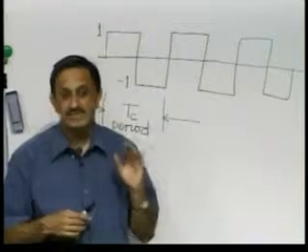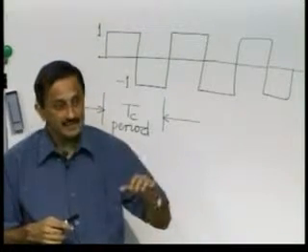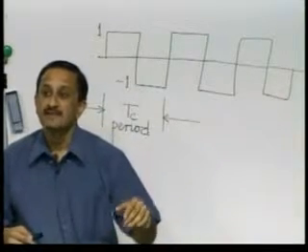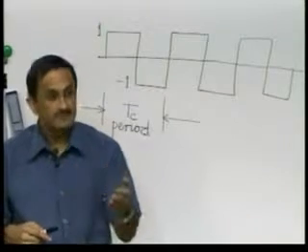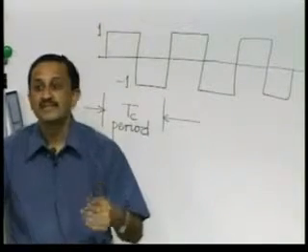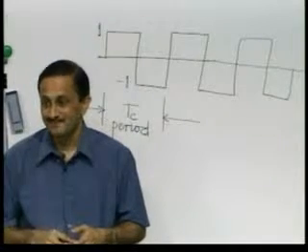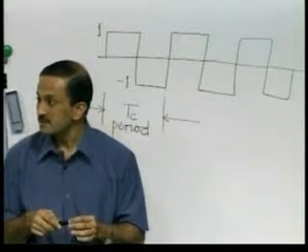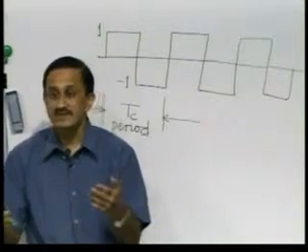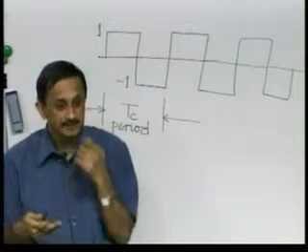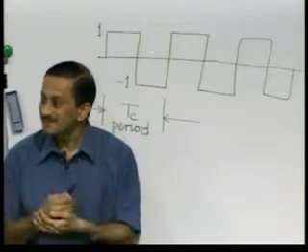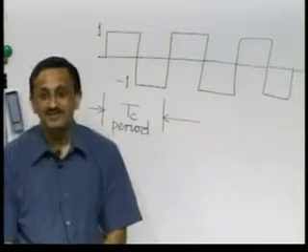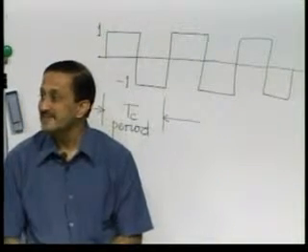Now, it is often much easier to construct a circuit that can cause gating rather than actually multiply a message signal, or a signal that we wish to transmit, by modulation with a sine wave. That is much more complicated. Multiplying a message signal with a sine wave in hardware can be a complicated operation. So, instead it could be easier to construct a circuit out of diodes for gating. In fact, even at your exposure you might be able to construct a circuit with diodes. I encourage you to think about it. Construct a circuit with diodes which can cause this kind of a gating operation.